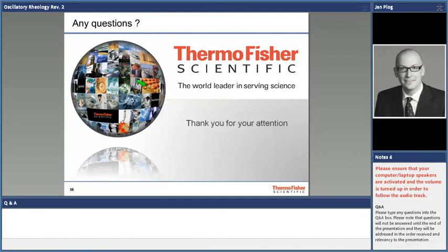There is another question from Rupa. If there's a specific geometry for the rheometer when doing oscillatory tests, this is, of course, not an easy question. All I can say is, let's say it depends. I mean, when you work with polymer melts and structured fluids, you of course do not want to use cone and plate geometries. You usually want to use plate and plate geometries, in order not to destroy or not to stress the sample too much when you actually achieve the measuring gap.